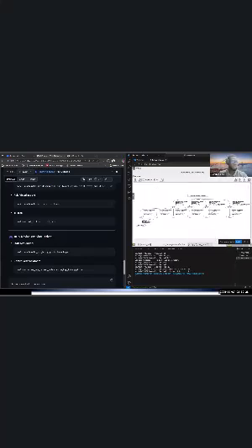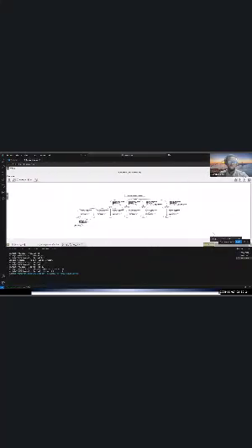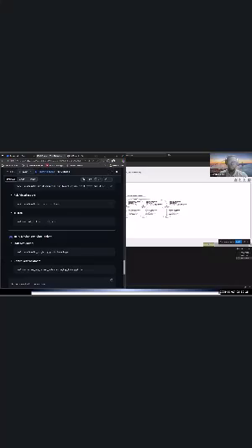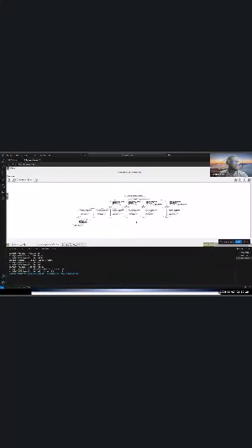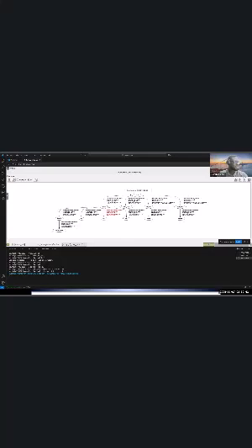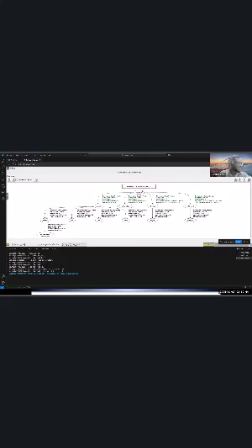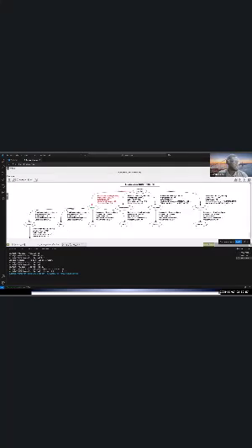I think we can make VS Code bigger now. We all have the link to the repo, so we can always look at it from time to time. I'll drag it to my other screen. Now look at the different links. You see the base link on top, then the chassis, the body of the robot, the caster wheel, left wheel, right wheel, LiDAR, camera, IMU. This is very important, so ensure it's working before you start doing navigation, because if this doesn't work, you will not be able to do navigation and so on.